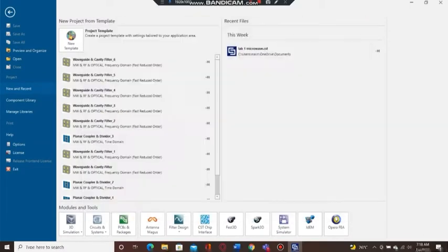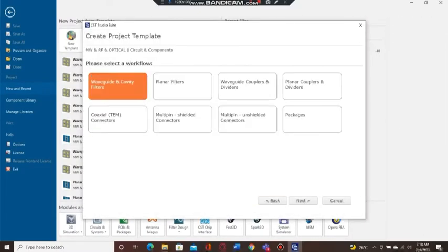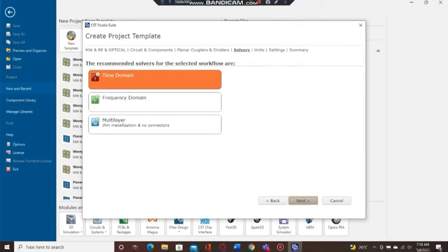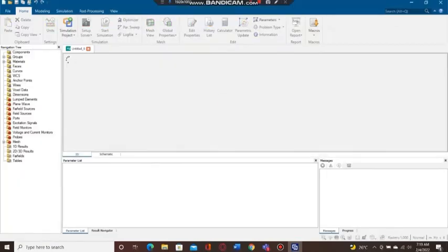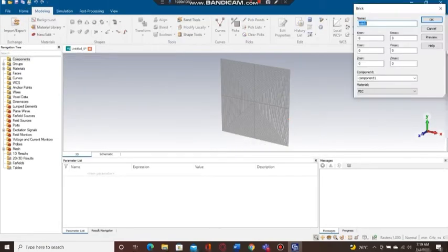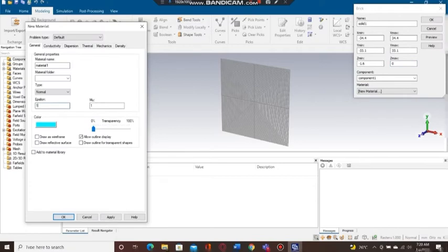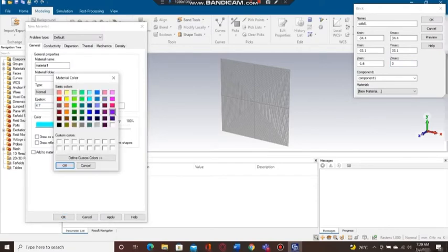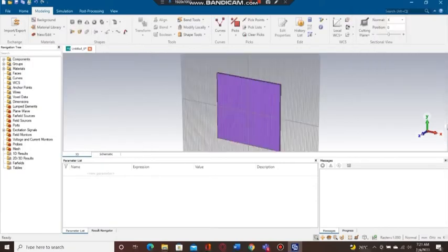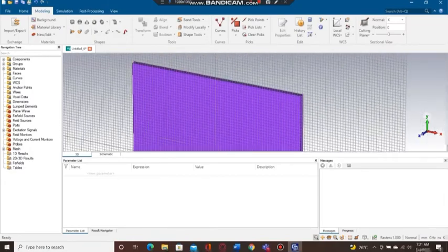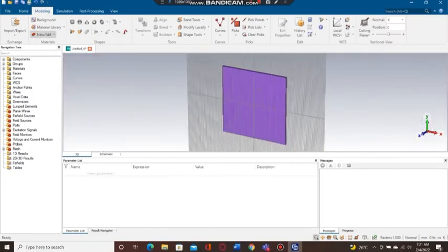This video shows the process of simulation of the T-junction power divider using the CST Studio software. We first need to set the range of frequency, which is 1 to 3 GHz, and later we need to create the brick for the substrate FR4 first, and we need to define the dimension, which is the thickness 1.6 mm and also the epsilon value of 4.7.